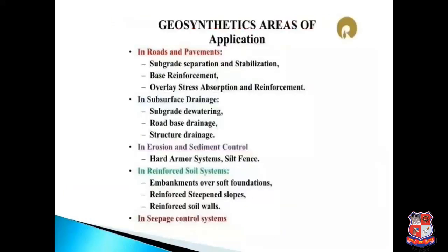Now the geosynthetics area of application. In roads and pavements: subgrade separation and stabilization, base reinforcement, overlay stress absorption and reinforcement. In subsurface drainage: subgrade dewatering, road-base drainage, structural drainage. In erosion and sediment control: hard armor systems, silt fences. In reinforced soil systems: embankments over soft foundation, reinforced steep slopes, reinforced soil walls, and in sewage control systems.